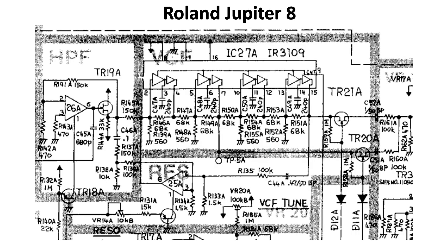This high-pass filter actually feeds a much more complicated filter that's a series of 4 one-pole low-pass filters using OTAs. This kind of configuration, where you have 4 one-pole filters in series, along with a feedback loop around the entire thing, is fairly common in synthesizers. So we'll look at the mathematics of that particular structure next time.